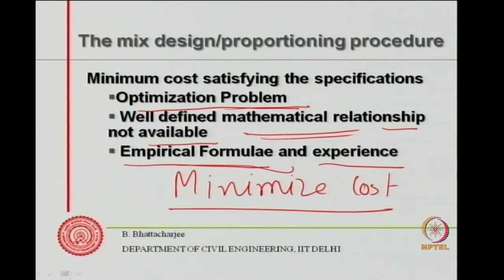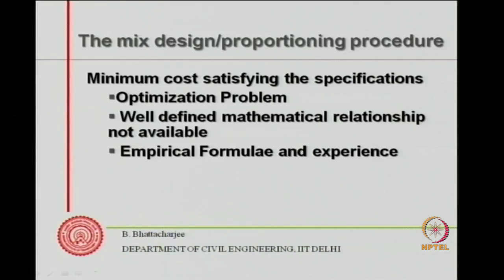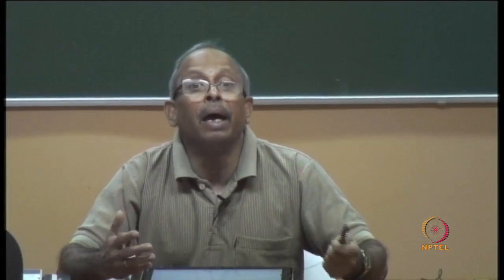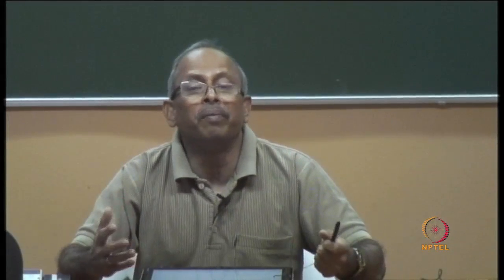So we must understand that mix design procedure is largely empirical in nature, and it is not only science, it has a large art component. A person who does mix design day in, day out for a given type of aggregate and cement system, or various cement systems in a particular locality, will easily come out with a mix proportion for any grade of concrete under that situation.